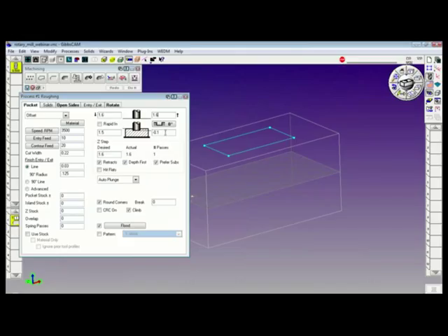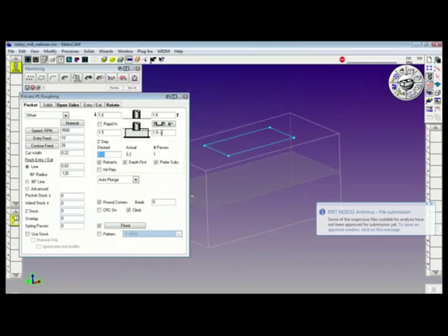Now my depth of cut, I want to cut 200 thousandths deep. As I previously mentioned, all depth values are positive from center line. See this black line here? This tells us that all the values are up from this line. If I want to cut 200 thousandths deep, I let the system do the math for me. I establish the top of the cut at 1.5, and I subtract 0.2. That makes the full depth of cut at 1.3. My desired step is 200.